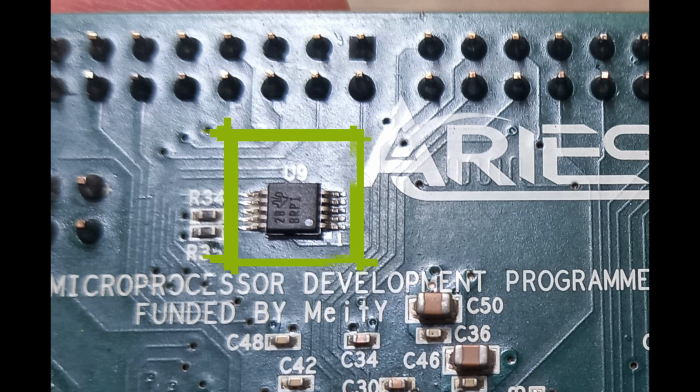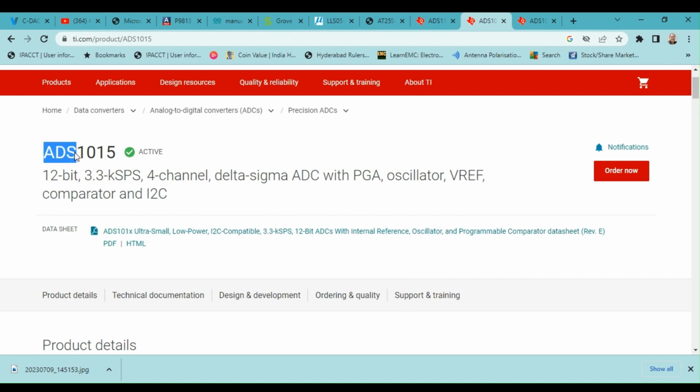If you are wondering where the A to D converter is located on the board, take a look at the bottom side. You will find this tiny 10-pin IC. I could not find any details about the ADC in the documentation for the Aries 3.0 board. Therefore, I did a bit of reverse engineering to learn about the device. From its marking on the package, ADS1015 seems to be the A to D converter from Texas Instruments that is used on this board.